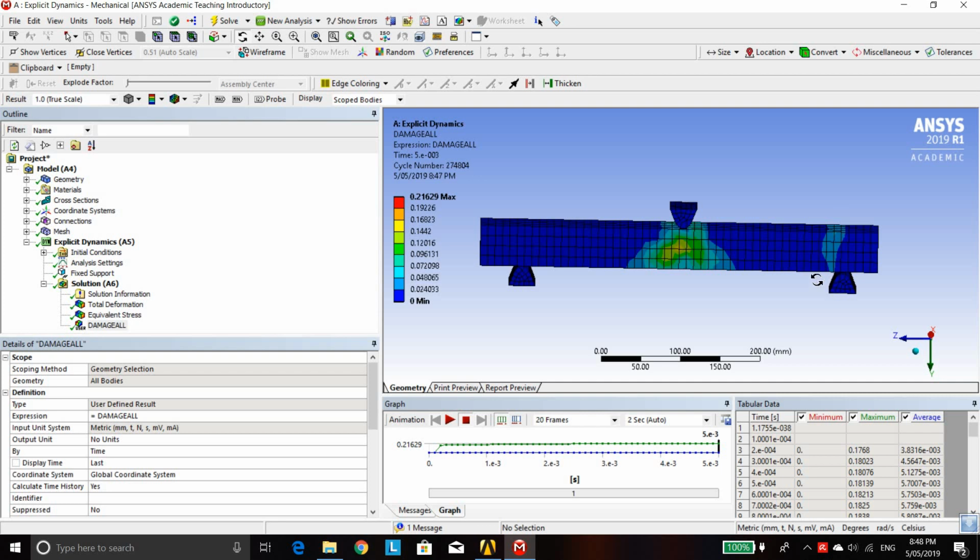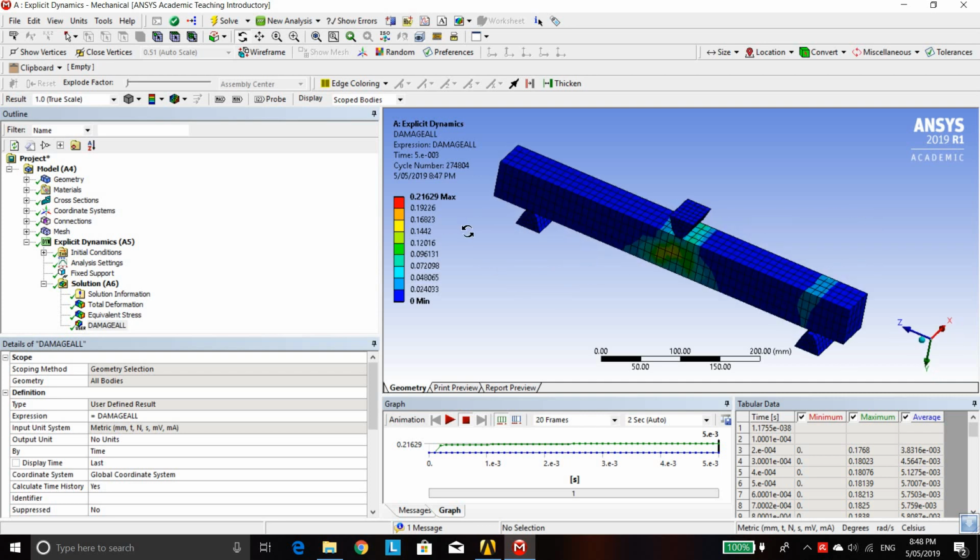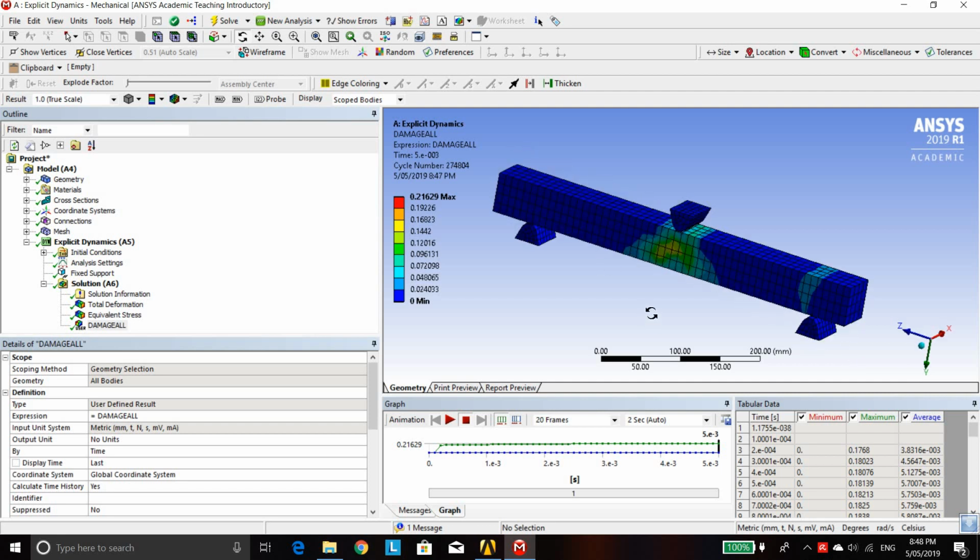So if we really had this slab with this geometrical arrangement, we are going to see some cracks, a lot of crack here and from the right side. And the highest is 0.2 damage. Okay, let's see rebars and then finish it.